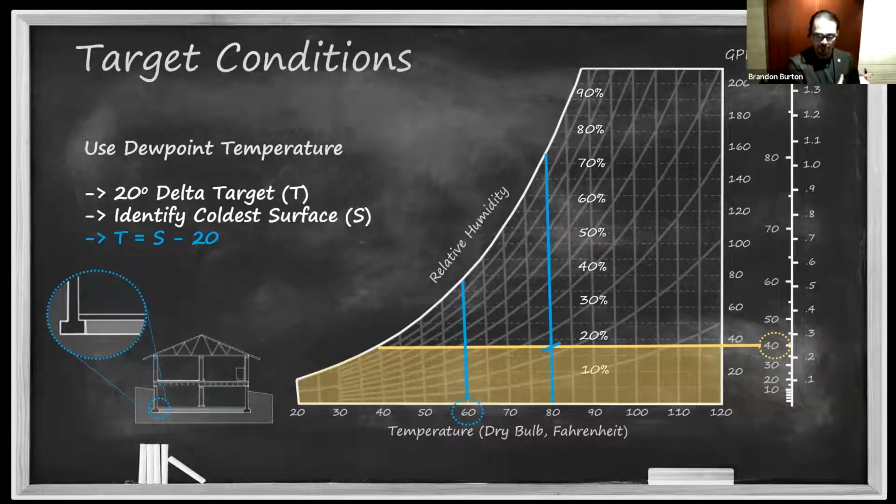Now, once I introduce my drying condition, hopefully we're going to be a little warmer than 60 degrees on most surfaces. Notice what happens here with that condition. Most of my surfaces, if I bring in air and maintain a temperature of 80 degrees, are going to see air at 80 degrees and about 22% relative humidity. You're going to have a lot of really good drying on a lot of those locations. And hopefully that 80-degree air brings the temperature of that 60-degree surface up a bit.